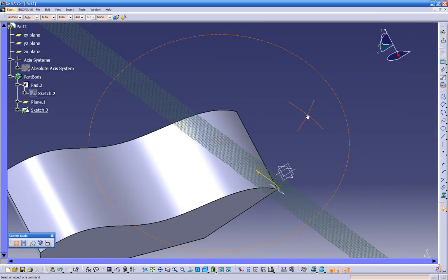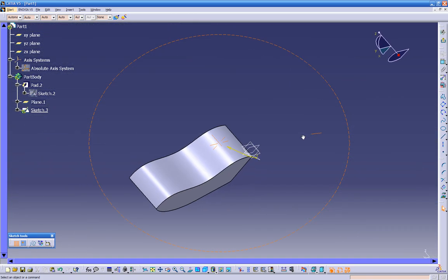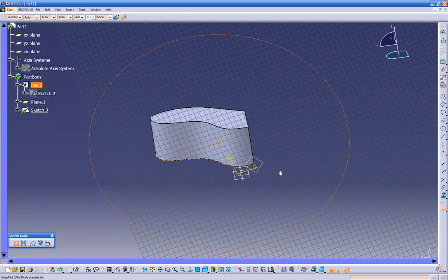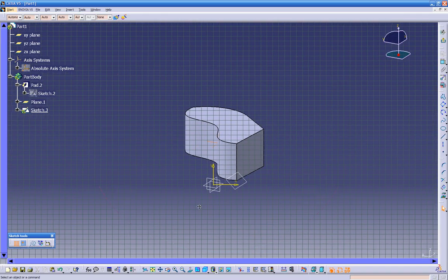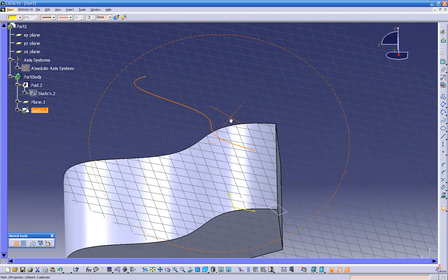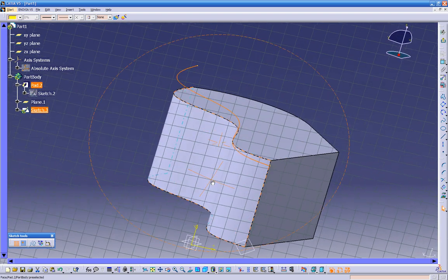So as you see right now, our screen, it's parallel with that plane that I just created. So let's click now normal to the view, and this is that option that I was just talking about. Click on it, and then click on the curve the way you like. And now watch this. If we rotate it, we can see our curve is projected into our view.